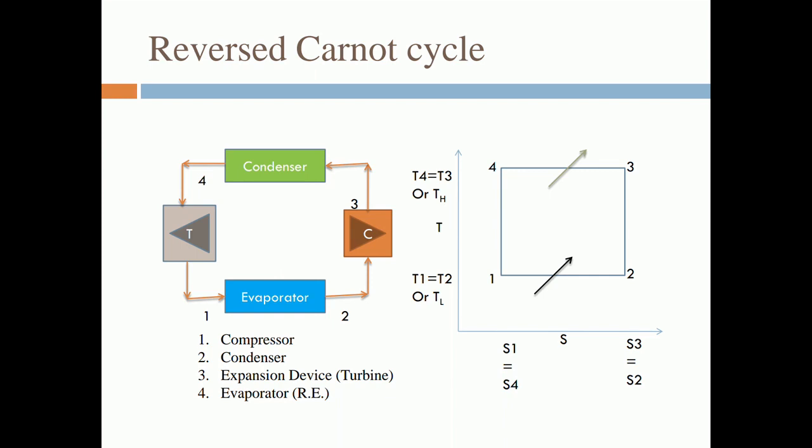Or if we put a substance to be cooled into the evaporator, when the working medium at low temperature and low pressure contacts that substance, the substance's temperature is reduced and we get the refrigerating effect. The working medium absorbs heat from the substance, so its temperature and pressure increase when it leaves the evaporator. Then it again enters the compressor to complete the whole cycle.